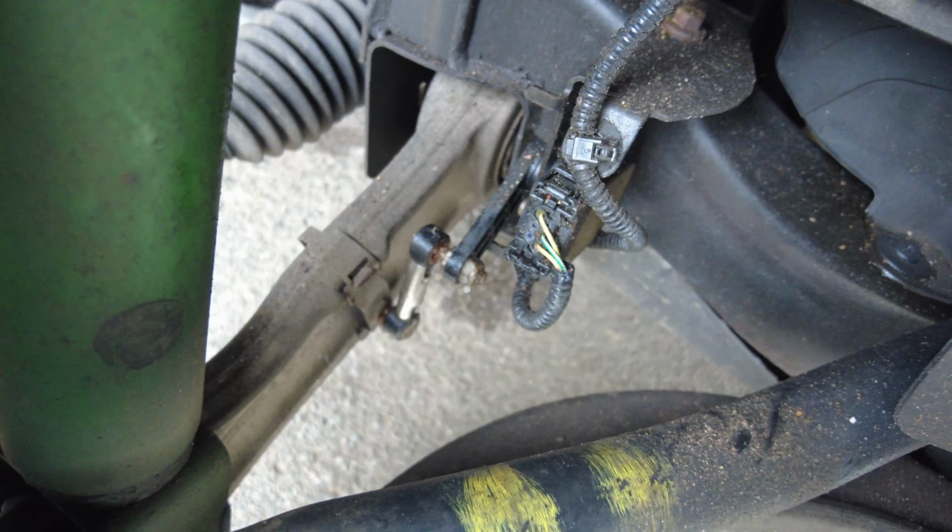So you can see here we've got 2 error codes. One says that there's no calibration or adjustment, and the other says the front level axle sensor is not plausible. So what we'll do is we'll crack into the setup and configuration settings, and we'll look to do front axle sensor calibration.